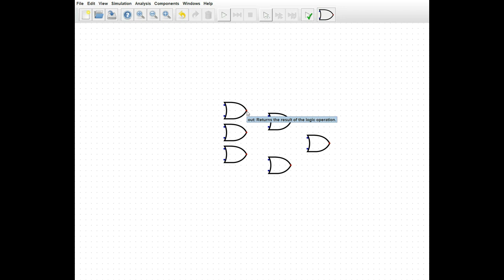For one of them, we're actually going to need an additional one. Actually, there's a couple of them that will need an additional one. But this is not too hard to understand, because if any of these signals are high, then the output is going to be high. And for just about every chip select I've ever seen, they're just about always active low.